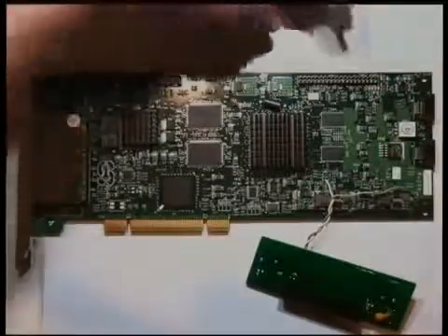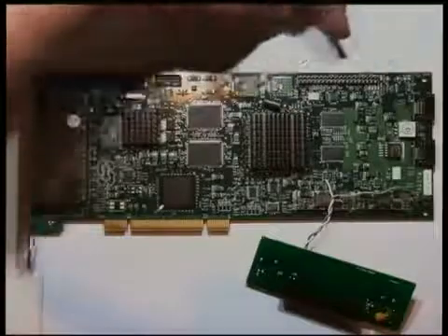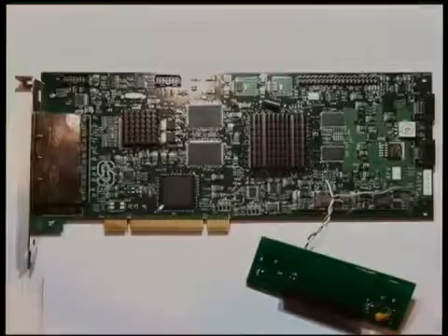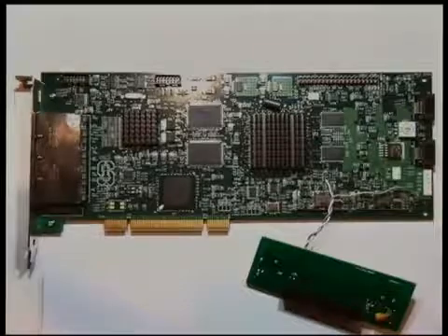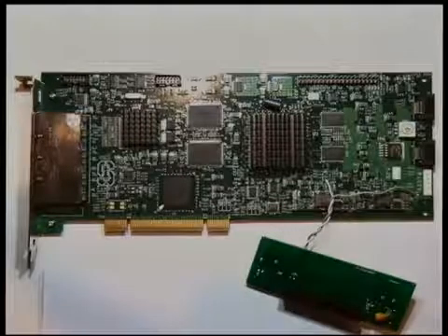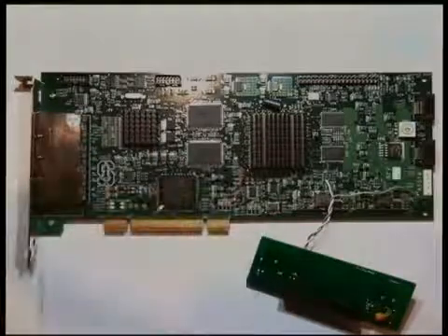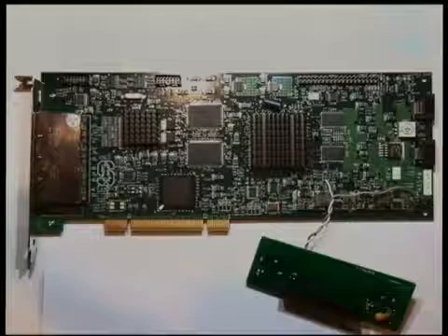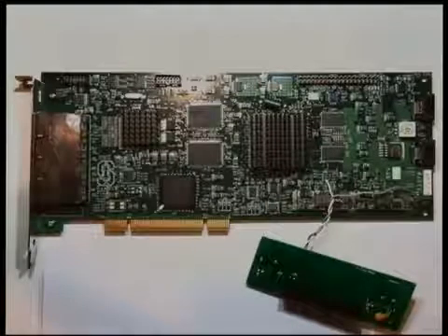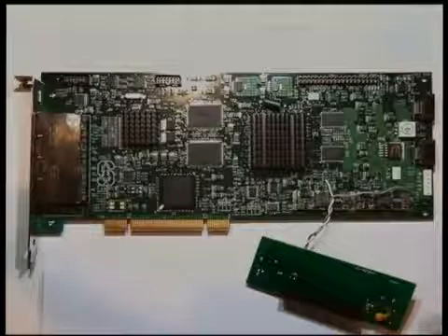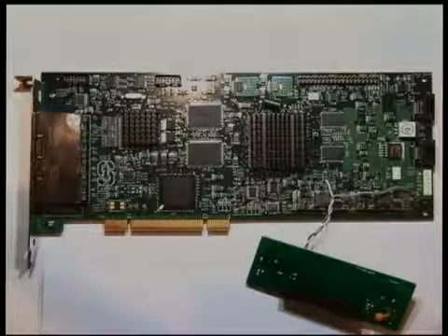And the interesting thing also is this 40-pin 0.1-inch spacing connector at the top here, where most of the pins are connected directly to pins off the FPGA. It says J4 actually, but elsewhere it says debug connector. And when I saw that, I thought, okay, maybe we can use that to do something interesting.